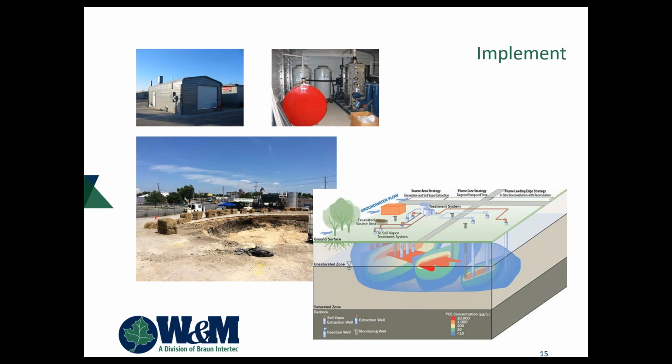it's not new now, but a brand new patent came out for a brand new product. That's a downhole product on the end of your drop tubes, which are like big straws that suck out groundwater, soil vapor, and the floating LNAPL. Well, they're generally fixed, and this product floats right at the surface of the LNAPL and will follow it down. If you have groundwater rebound or some kind of influx, it follows it back up, so it limits the amount